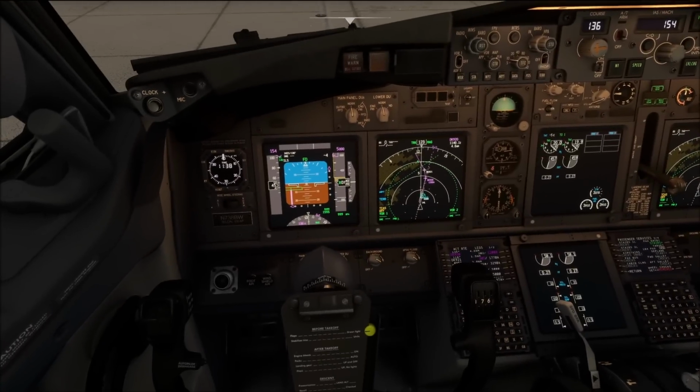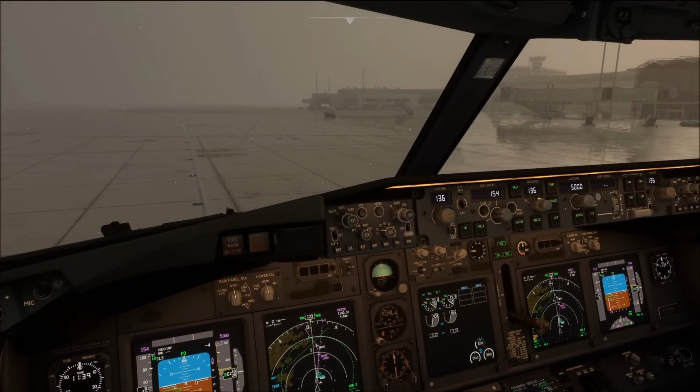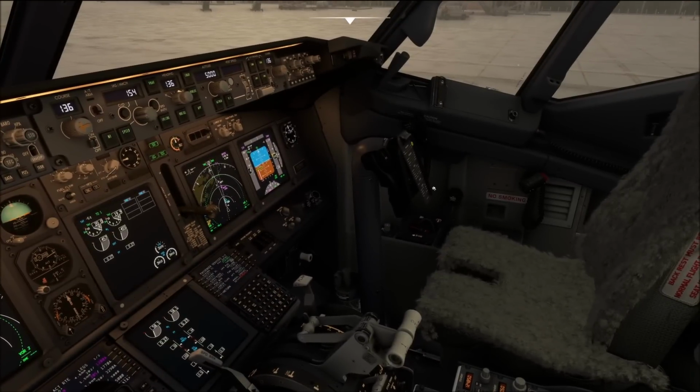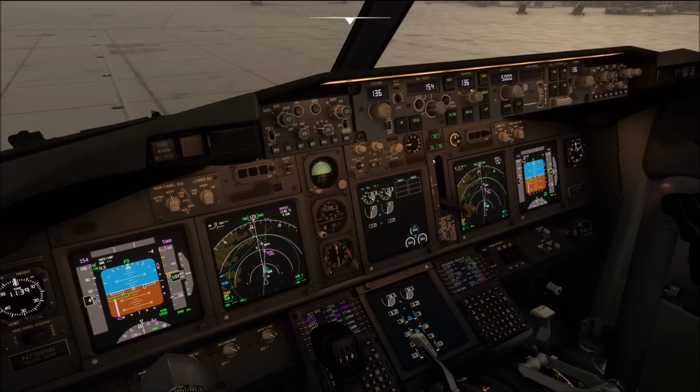The same goes for the flight control check. In case the aircraft is exposed to freezing precipitation as it is at the moment, we are going to delay the flight control check until we reach our runway holding point and there is no further delay expected for takeoff. In my airline, in order to be absolutely certain that you don't forget that your airplane is not configured for taxi, the first officer would clip the winter operations checklist to the decal checklist on the control column up here, so that you absolutely have it inside and that you are aware that your aircraft is not configured for takeoff.